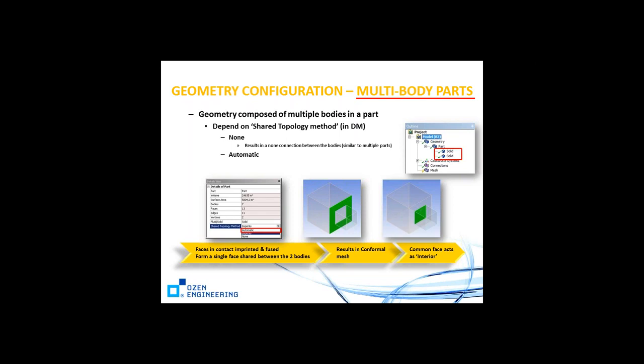And if you're doing FEA, again, you can specify a different material property here, different material property there. If it's CFX or Fluent, again, it will be a continuous mesh, and at the interface, you're going to have nodes right at that interface that will definitely define the connection point between the two cubes.